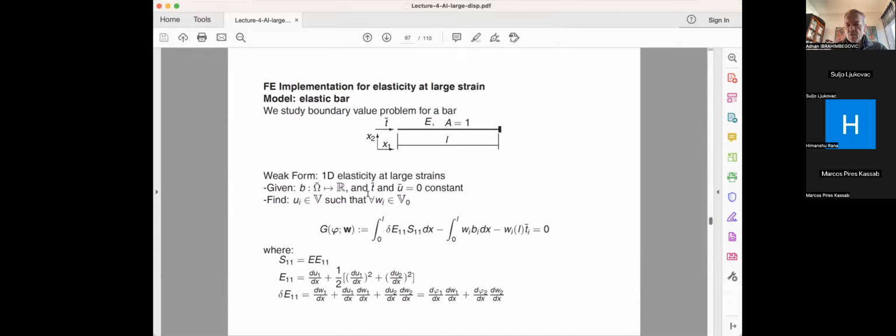So if you really want to bring all the power of this formulation, you have to at least consider a 2D problem. And so not only 1D, but 2D type of formulation. So basically, I claim that you have only one displacement, so one strain component. This is E11, and one stress component S11.